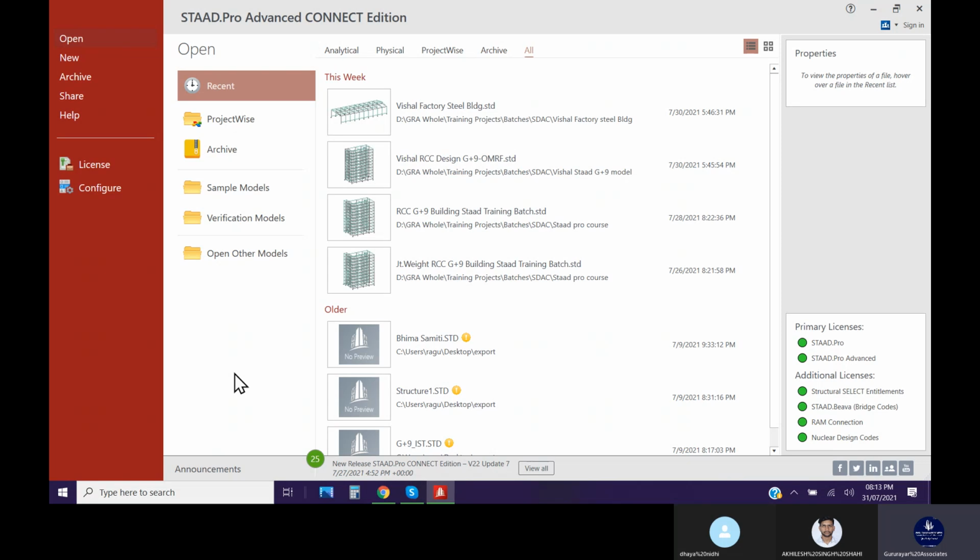It is cast in situ, but it is not coming together as a concrete member. First the concrete member, column or beam, will be cast. After that, separate shuttering for that decorative work will be made. Then it will be poured slowly with that 6 mm chips concrete and then molded. So it is separate.